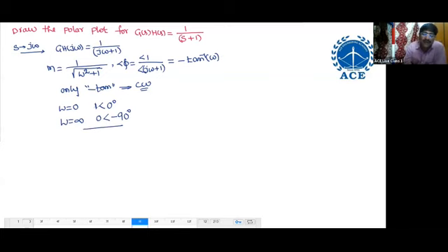Is our condition satisfied or not? The magnitude at omega 0 is greater than the magnitude at infinity. That means satisfied. Always check the magnitudes and put the tick mark, so that we can identify whether our procedure is valid or not. In case the ending magnitude is more, then our procedure is not valid. Equal is also valid, but it should not be less.